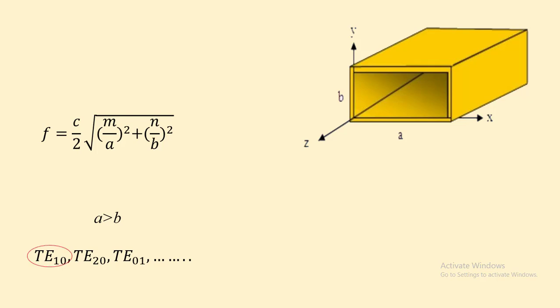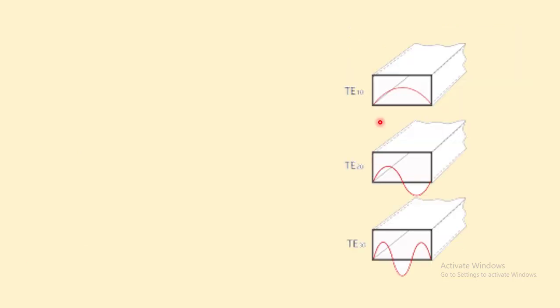The best working frequency of a waveguide is the range where the first mode is excited and the second mode is not excited yet. Since as the modes increase, the power of the wave should be divided between them and the efficiency of the waveguide decreases. So, for a rectangular waveguide, the bandwidth will have such a range. As can be seen, the bandwidth is 1 octave.